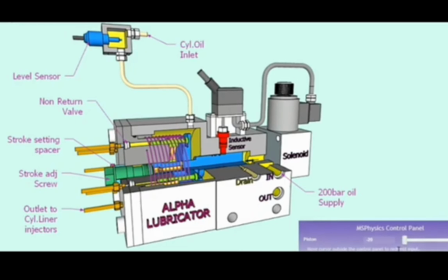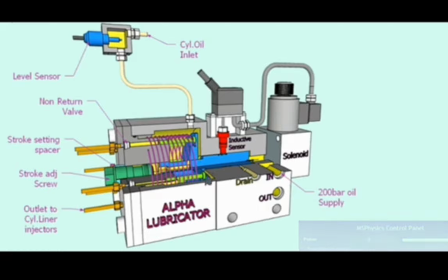It is also fitted in the same hydraulic control unit, activated by the same high pressure oil, and it has a main piston with multiple small pistons which give the supply through non-return valves to the respective quills on the cylinders.